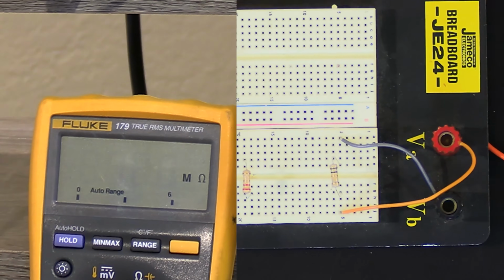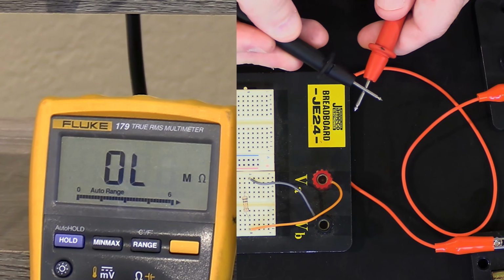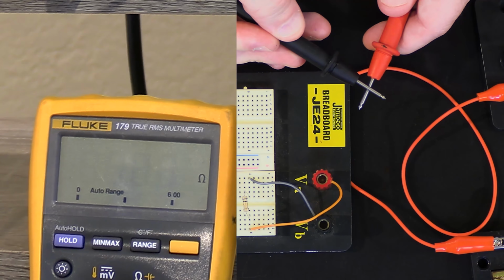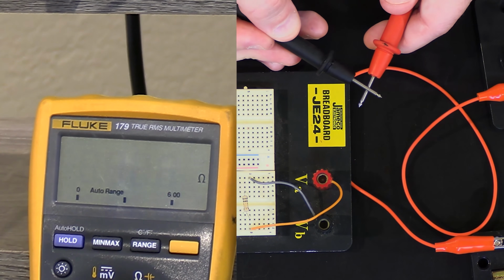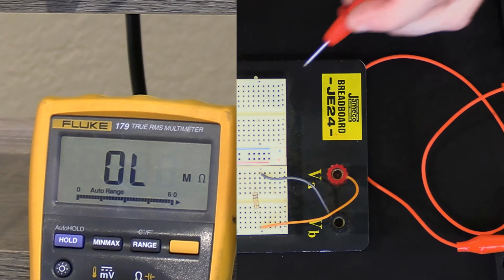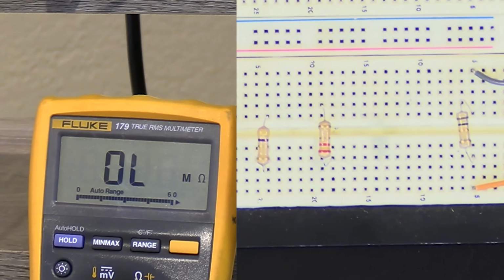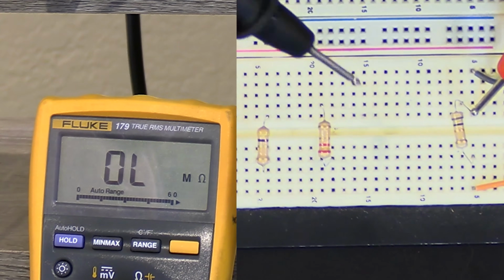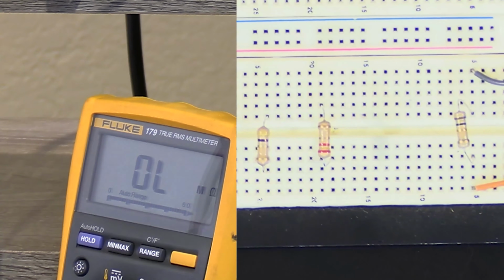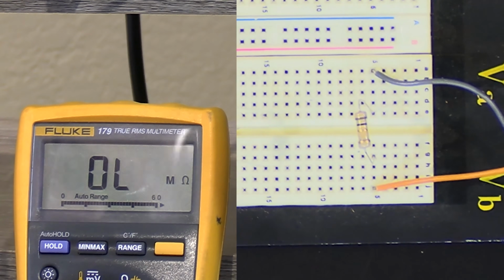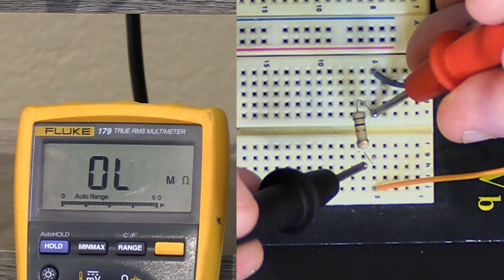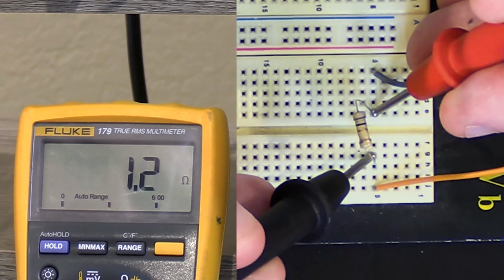nothing. If I touch the two leads together, it's not measuring any resistance; you can see on that display it's bouncing between 0 and very, very low. And then I have this thing connected to a breadboard. I'm going to talk about a breadboard in just a second, but for now, notice that I'm going to touch one side of the resistor. Whoops, kind of messed up my little meter over there. Sorry about that. I'm going to touch one side of this resistor, and then on the other side I'm going to touch the other side of the resistor, and I'm going to see what it says.